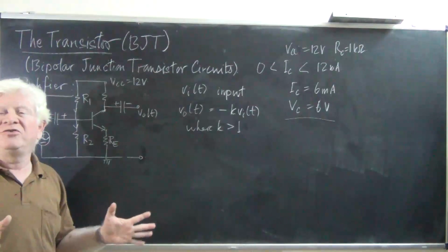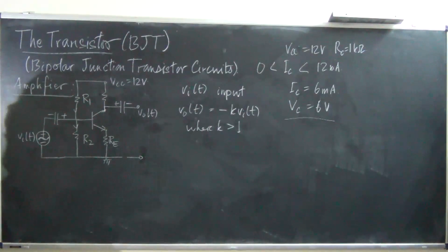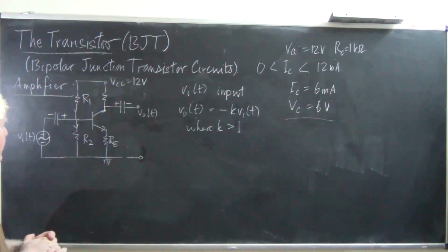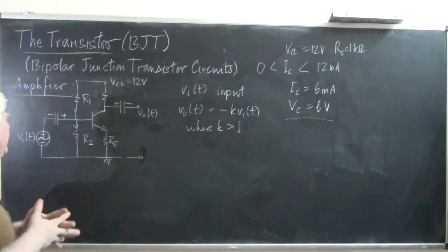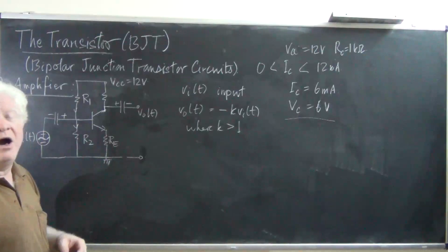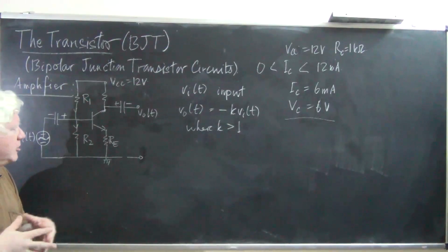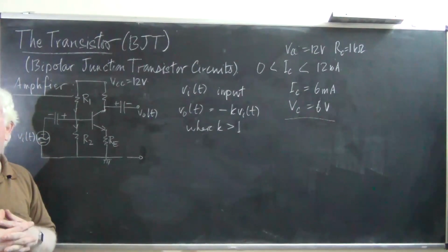So much for the amplifier's behavior. More details are available in the handout. There are a few last comments to make. As I said, there is a certain loss of amplification due to the presence of RE. But for reasons that are a little complicated to explain, the presence of RE does improve the behavior of the transistor circuit. Now let's see.